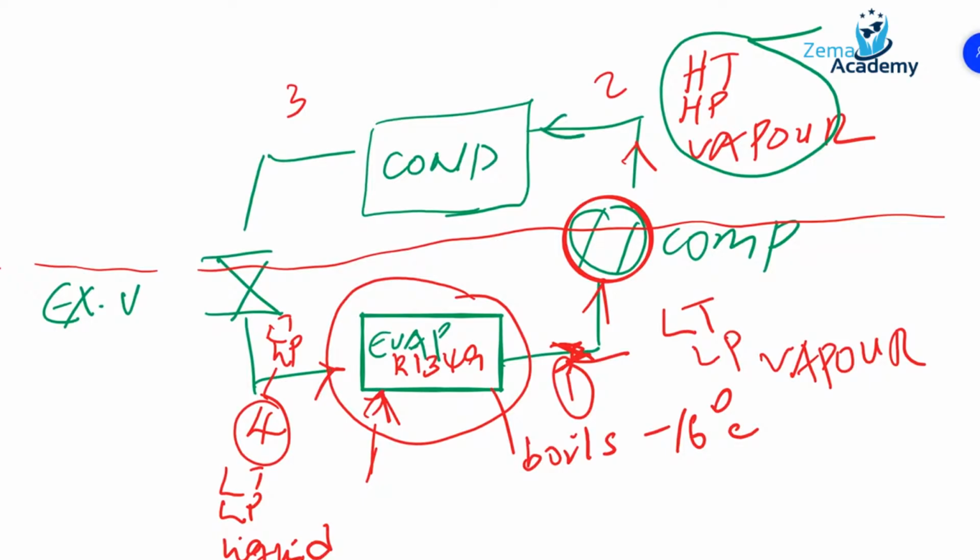By passing it through the condenser, you're sinking that high temperature and high pressure. So here you will have a secondary circuit to remove the heat from the condenser. And again, we will look at whether you're using air or water to remove the heat from the condenser. And that's how a condenser is classified, based on either air-cooled or water-cooled condenser.